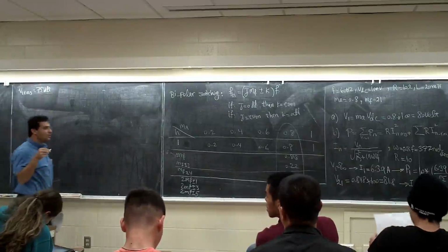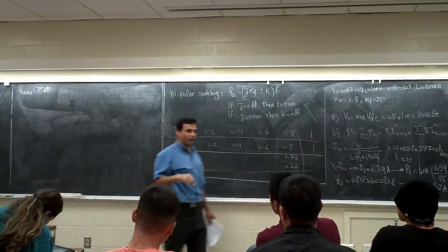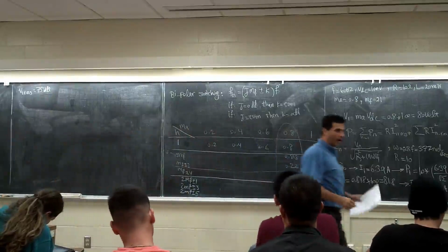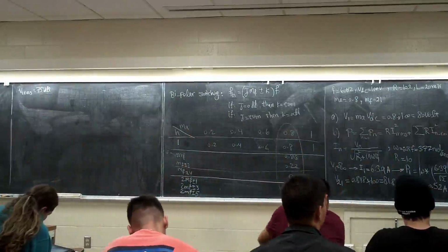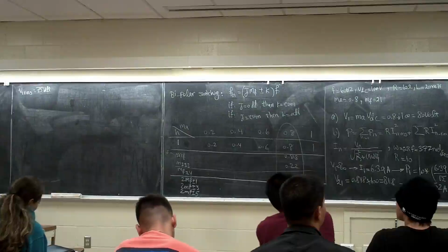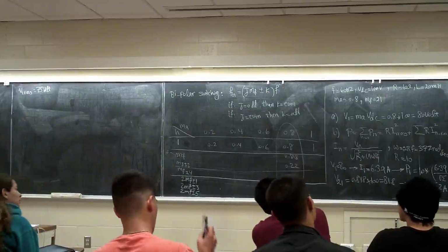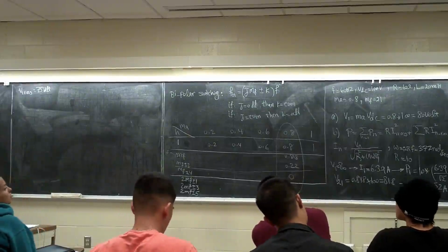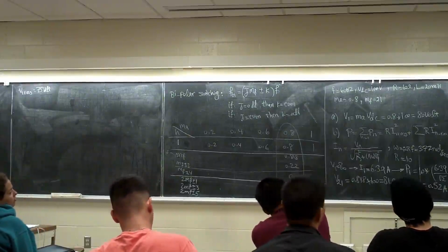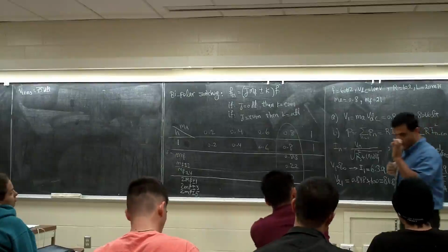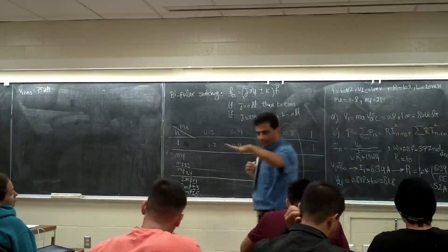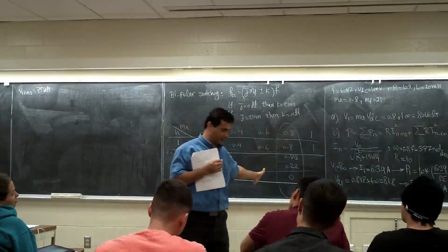See, when you say the output is 75 volt, it's not the third harmonic or the hundredth harmonic. The one we care about is the first harmonic, right? When you have 60 hertz, that one is important. You don't care how much is the 180 hertz, 240 hertz. You want them as small as possible. The one you want to have, the 110 volt, is the 60 hertz, right?